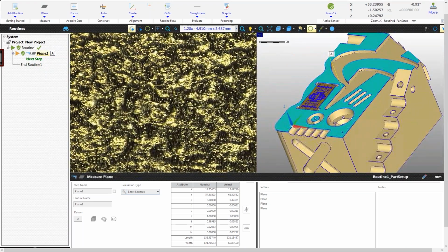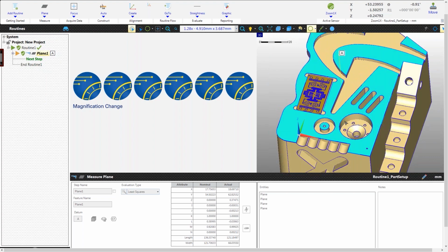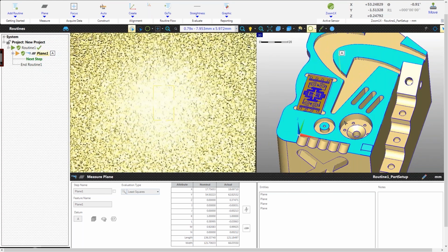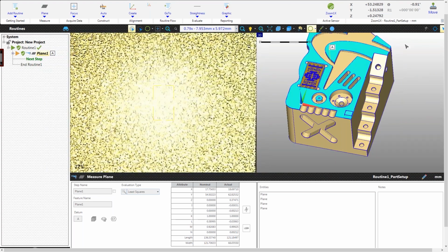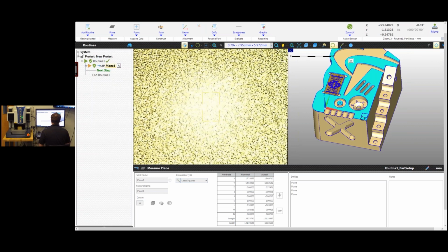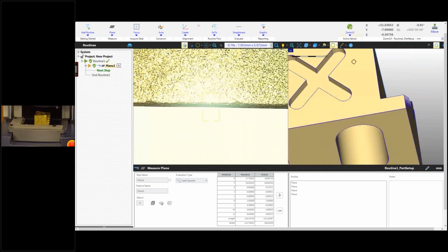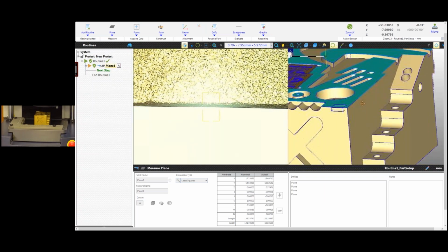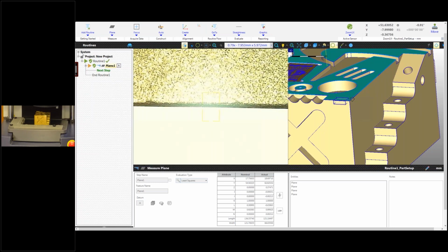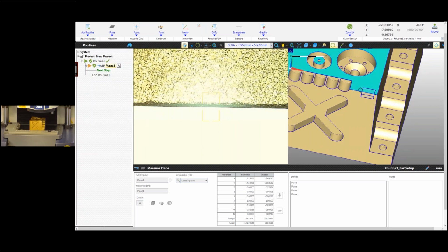Okay. Next thing, I'm going to zoom out. And I'm going to use this little move to location mode. Everybody see that up here? Once I'm aligned to my part, like I am now, I can use this to drive the machine around. It will, if I click on the bottom side of this, try to drive down there, so don't do that. Be aware that I've got about a 2.5 inch, 3 inch standoff from my optics to my part, but this part might be tall enough to actually crash into it. So just be careful when you're using this.